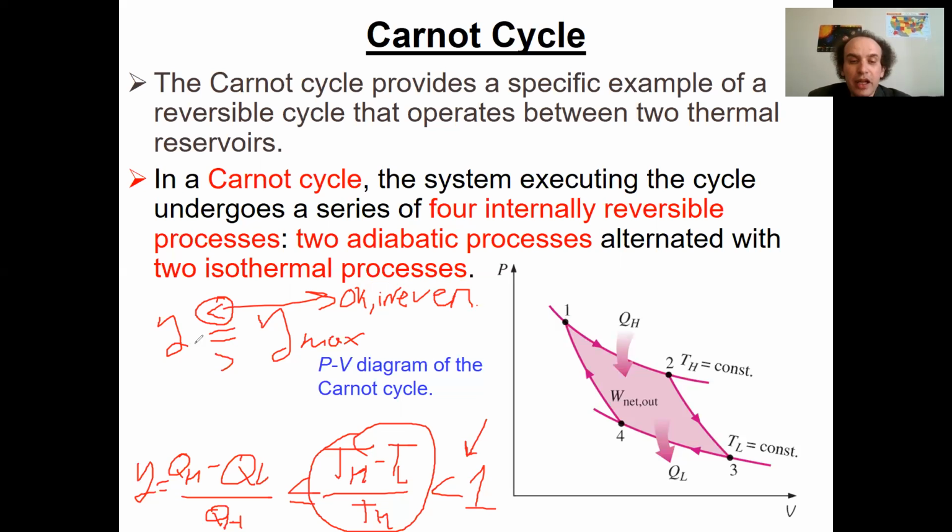Correct? If your efficiency occasionally appears like this, what can you say from here? You may say that it's theoretically possible. It means that you deal with a reversible cycle. So your cycle is a Carnot cycle. May it happen? I would not invest money in this because it happens seldom, but you cannot decline it.